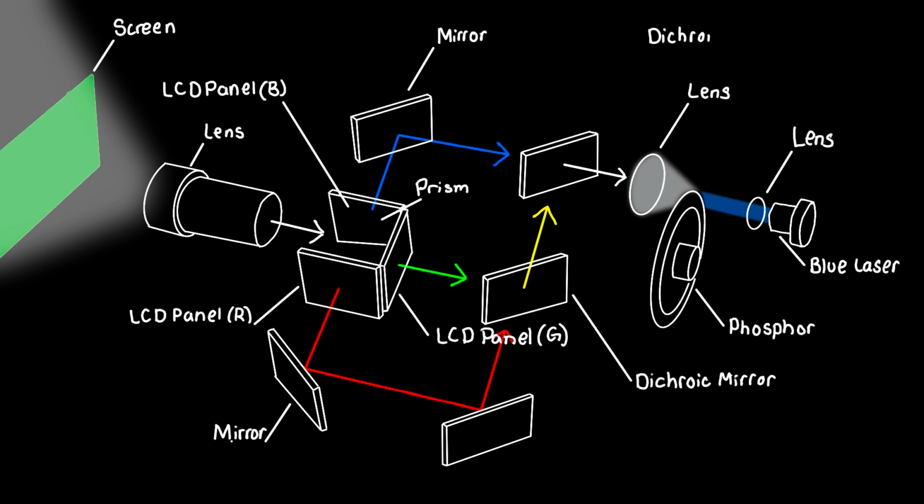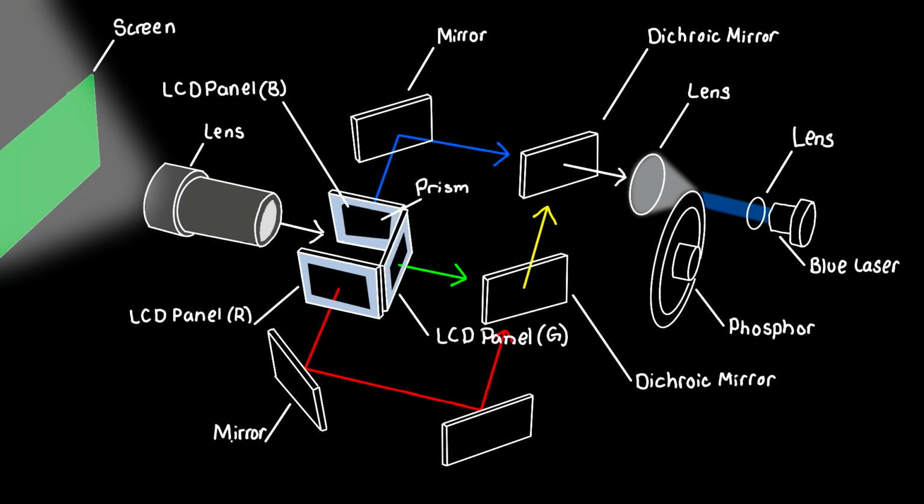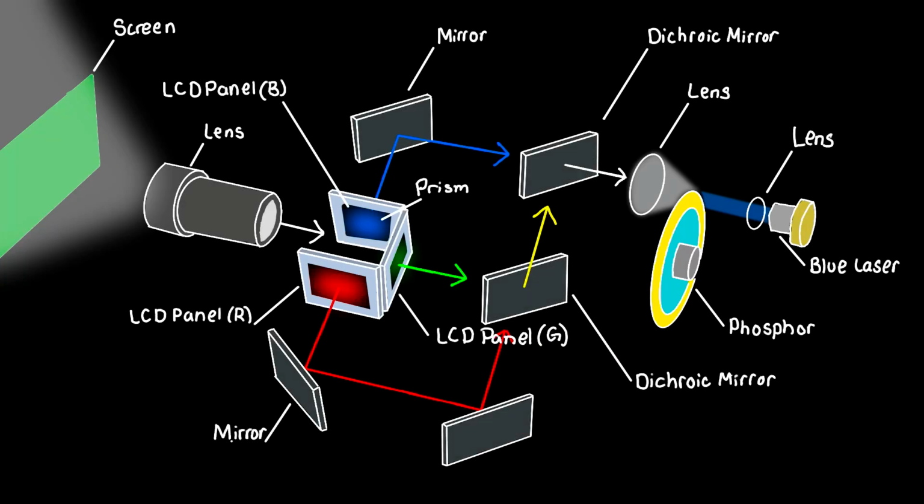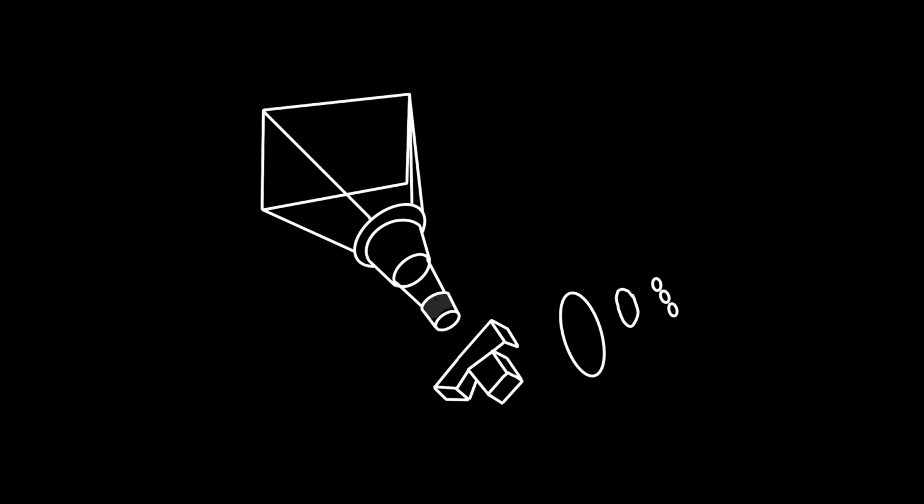The blue laser diode shines through a yellow phosphor wheel to create yellow light and is then filtered to separate blue and green, while the red laser diode is introduced after the phosphor wheel. These hybrid laser projectors outperform lamp-based projectors in brightness while delivering superior color and long life.